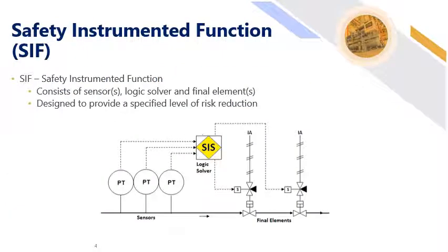A SIF is made up of 3 different parts. The sensors, which can be individual or have a set of redundancy, the logic solver, and the final elements, which again can be individual or be in a redundant configuration.